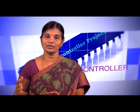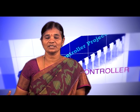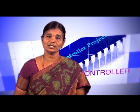So, these are the instructions used to perform the arithmetic addition and subtraction operations, along with multiplication and division also. For division and multiplication, the two data should be loaded in the accumulator and B. In case of addition and subtraction, you can load one of the data in the accumulator and the other from either immediate data or register data, or you can also use memory access.